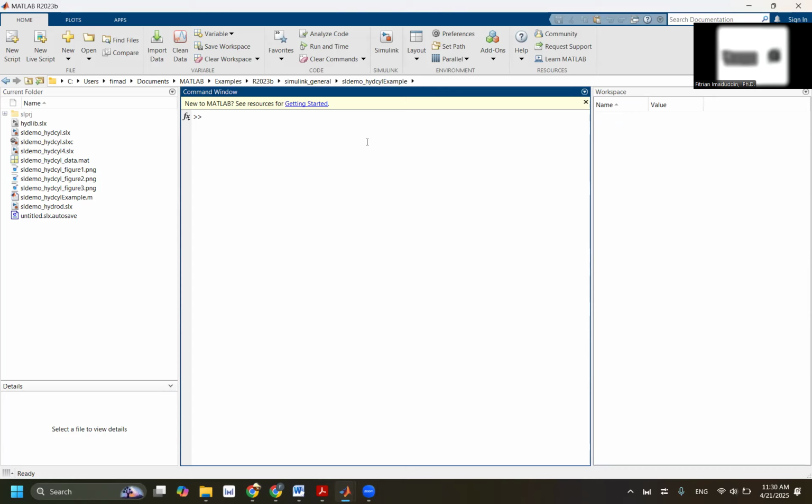Everything in Simulink, if you have a variable, if you have any constant, they will check the library in the workspace. So if it's empty, the red colored message will appear. So we need to make a definition here. What is M1? M1, just like our example earlier, I want to equal to... So you will see it here. M1 is equal to 1.